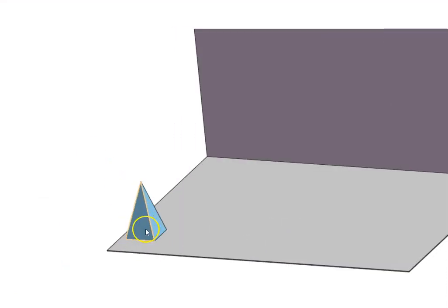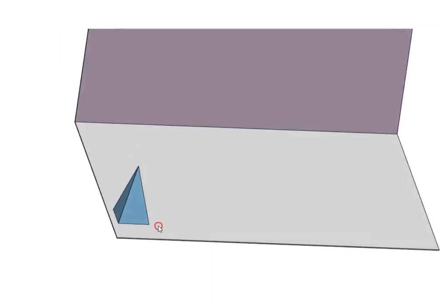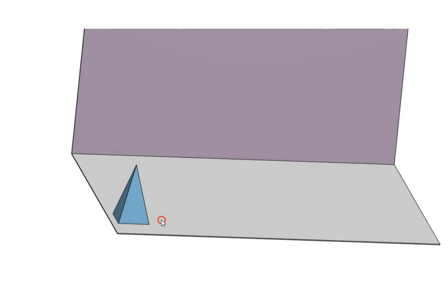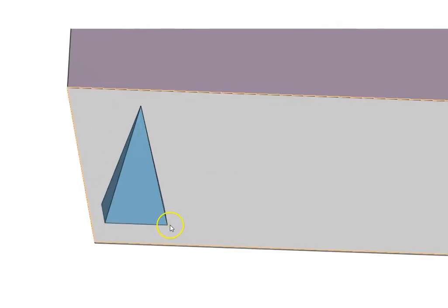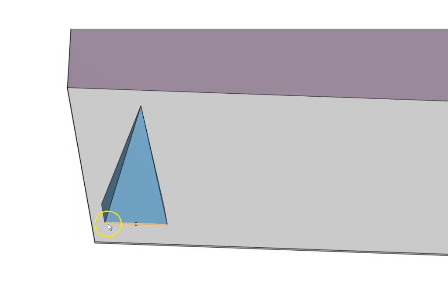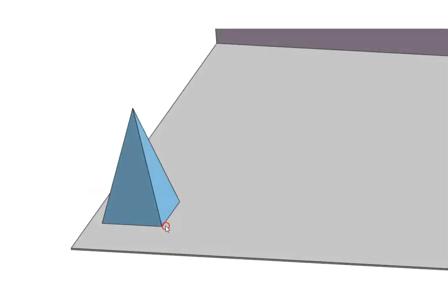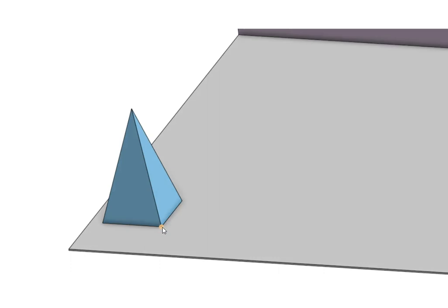What you see on screen is a square pyramid which is simply resting on its base. The question specifically says that it is resting on a corner, and at the same time one of its base edges containing that corner. For example, if we rest this on this corner, then the edge containing that corner would be this one or this one. Any of those edges should be tilted with the horizontal plane at an angle of 30 degrees.